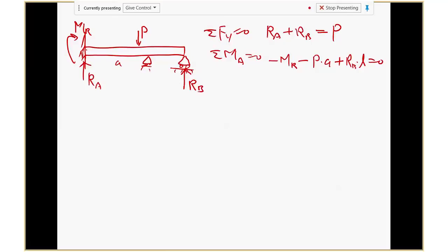So if you have 2 extra unknowns, the degree of indeterminacy will be 2. If you have 1 extra unknown, the degree of indeterminacy will be 1. Imagine you can have many supports here. Then you can have 5 degrees of indeterminacy, or 4 or 6. And that's actually happening in real world structures.